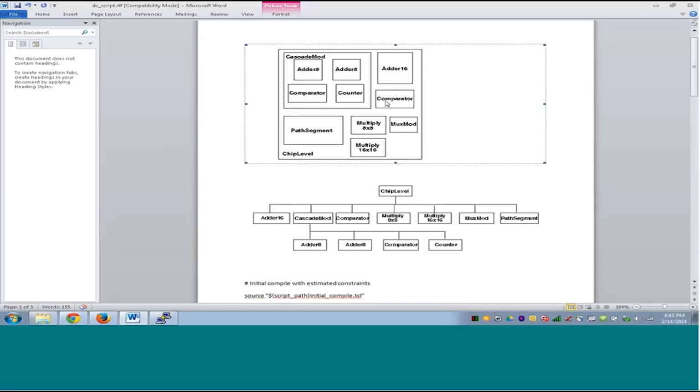But the major concern is regarding the blocks themselves. Let's say I am synthesizing USB, which is part of my chip. I need to have good timing constraints for USB. If I am synthesizing CPU, any block I synthesize that is instantiated in my chip should have good timing constraints, because the optimization depends on that.